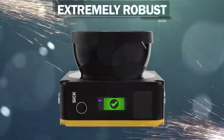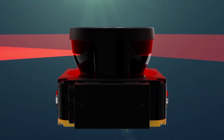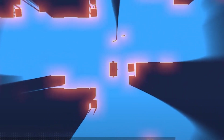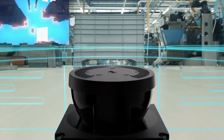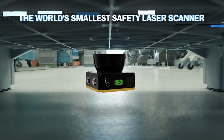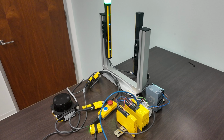What makes NanoScan 3 really special is the super compact size, with a height profile of just 3 inches, which makes it a perfect fit for AGV applications where space is always a constraint. We also have 3 meters of protective range on it and 10 meters of warning range. Along with that, we have various different variants to match the specification of your application.